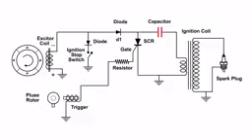in one direction. And as we continue and get to another south pole, we have the polarity again, negative on the bottom and positive on the top, and D1 conducts, and we get a little more voltage in that capacitor. And again, we don't have anything until we get to another south pole. And we have a little bit more voltage put into that capacitor.